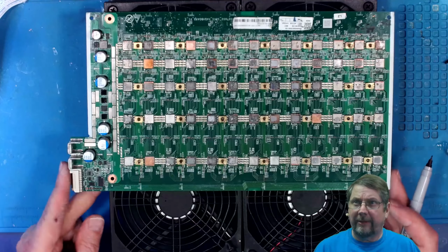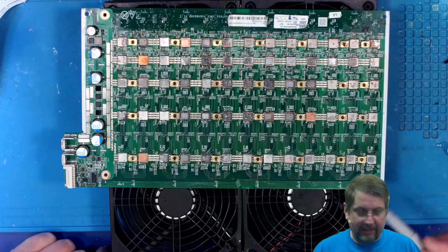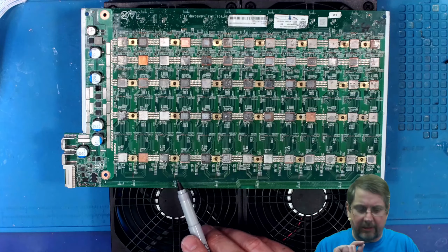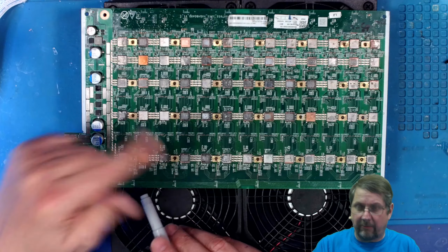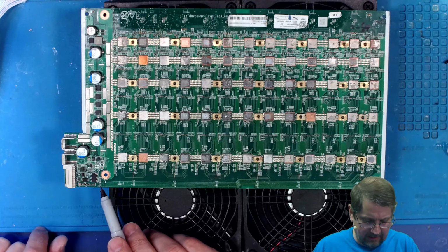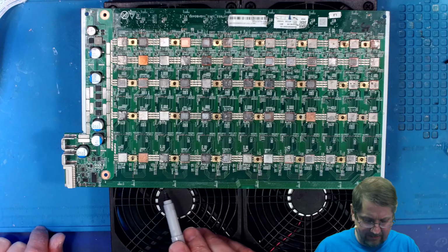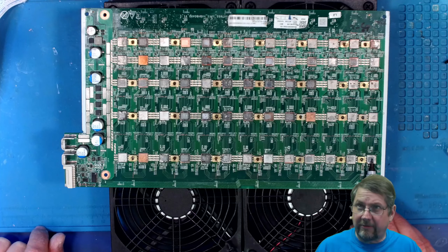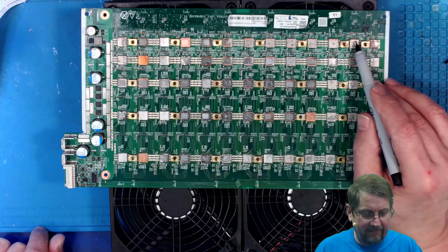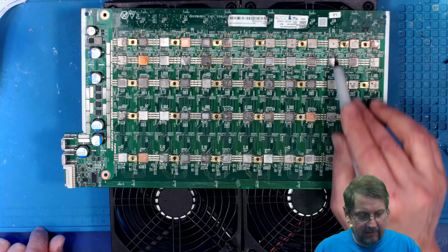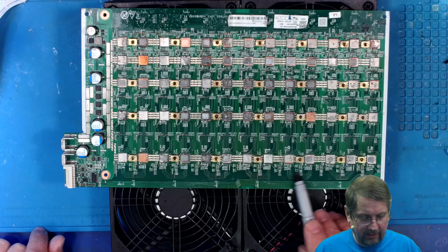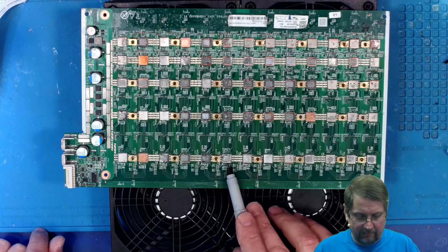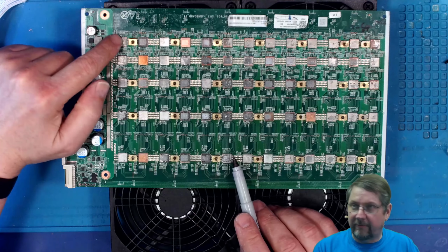Remember, for anybody who is new to this, on the S17 Plus, the signal comes in this way, with the exception of RO. All the other signals, RO flows backwards, but everything else you see come in on the traces. The traces are right here along the edge of the board. So this is the input of the traces. They turn down. This is chip 1. Chip 1, chip 5, chip 6, 10, 15, 20, 25, 30, 35, 40. You just follow the traces and you get all the way over here to 65.